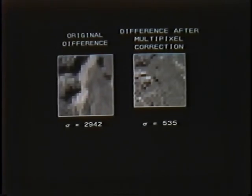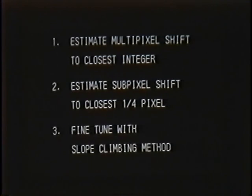We also need to calculate the fractional part of the shift, the subpixel shift. Estimating subpixel shift is considerably more complicated. A paper entitled Subpixel Image Registration by Kwai Tan provides a complete analysis of various methods which have been proposed or which are in use to measure these small shifts. The second step of the estimation process, used for background stabilization, is a method Tan calls intensity interpolation.